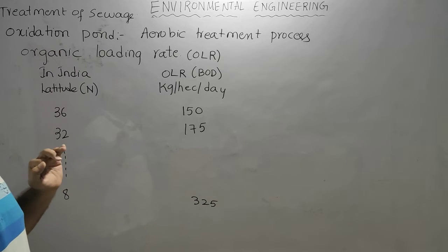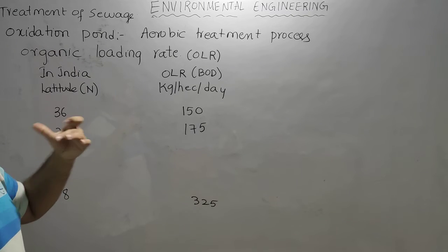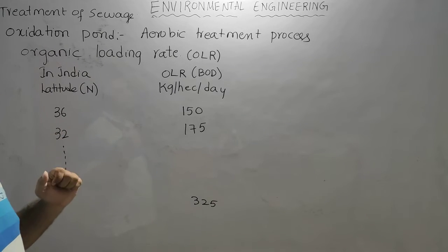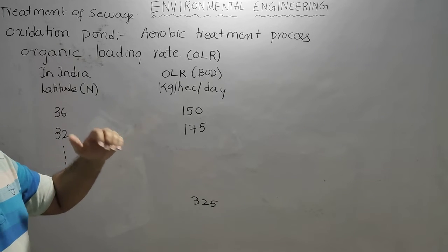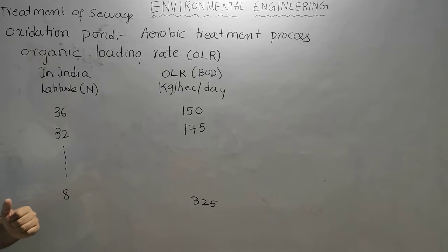Now, how many days are you giving the tank for the detention time, for the decomposition process to complete? Depending on that, we can design the oxidation pond.